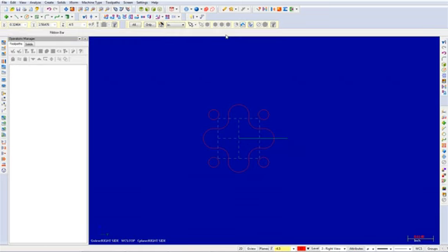Your part will appear as shown. Now we will create points. First, select the isometric view from the toolbars. Select the Create Point Position command and then pick Fast Point.